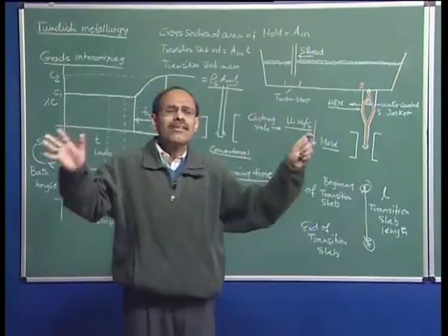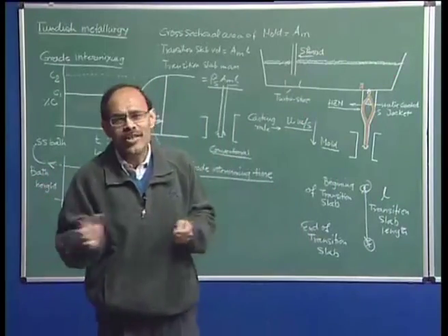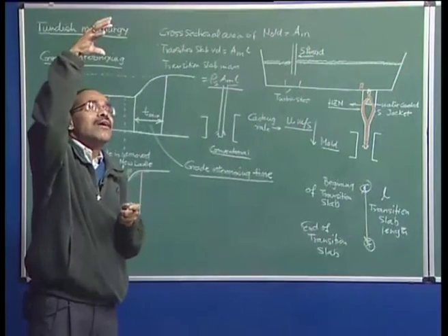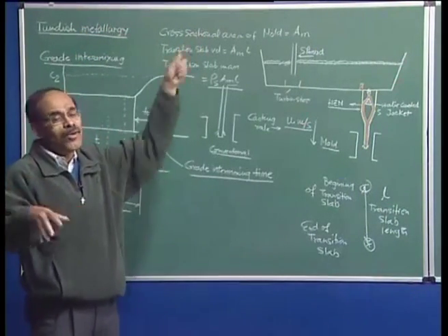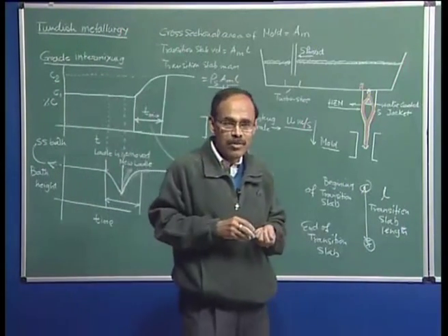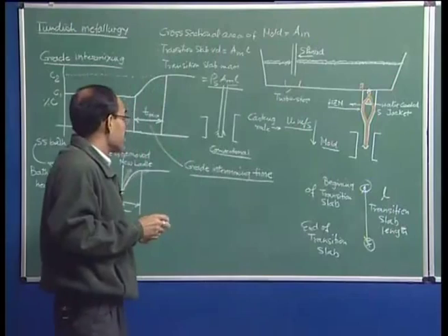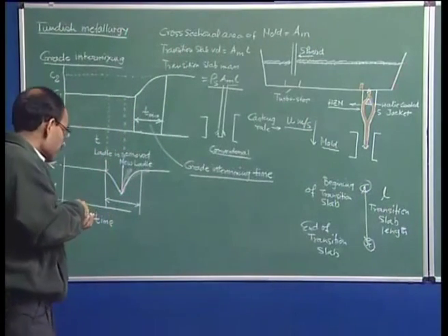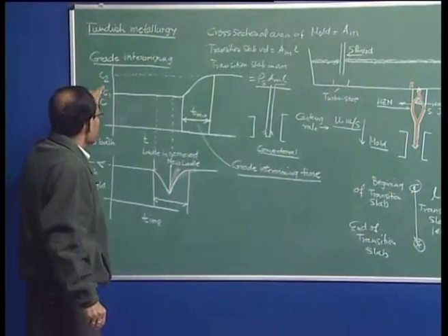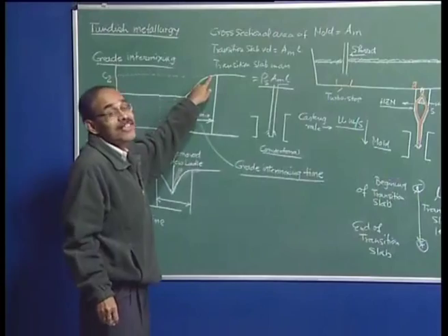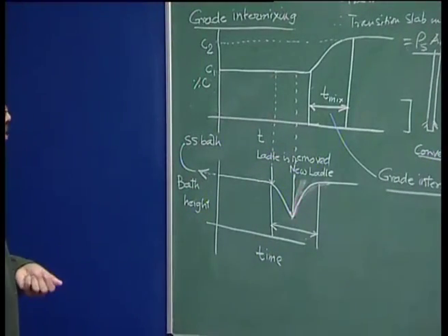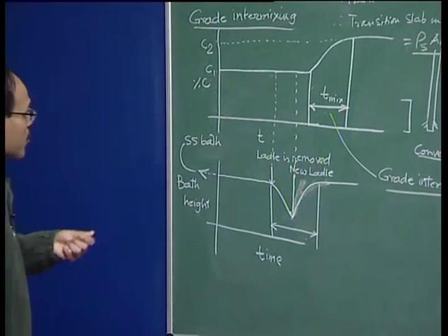If you are casting primarily plain carbon steel, it is not such a big deal, because if you are casting 0.14 percent carbon and 0.28 percent carbon, you will always find a buyer who will take that intermediate composition of carbon, but it is not true when you are making alloy steel. So, how do you understand this? How do you generate this curve? This is a very important issue. This can be done by modeling, which we will be discussing, or demonstrating, through a few lectures.